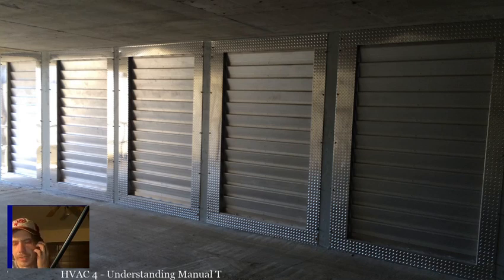Then you may have to give that thing more air, but obviously first you check that the blower inside of the VAV is working properly and it doesn't have a dirty air filter and yada yada. But that is what you're looking for in something that cycles on and off, is some kind of airflow issue.